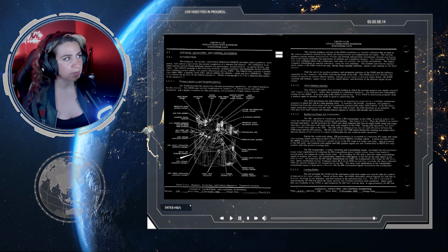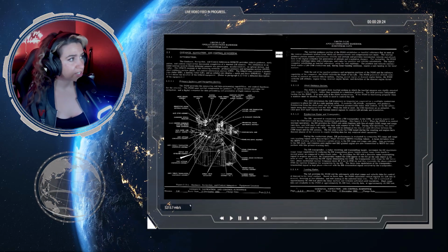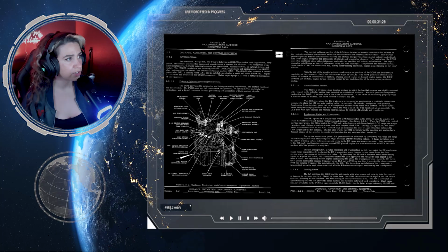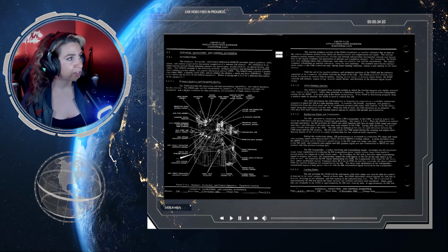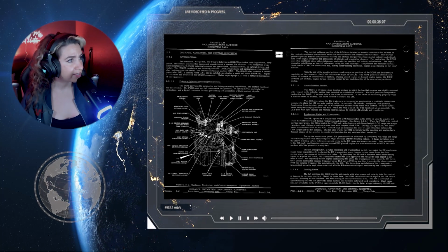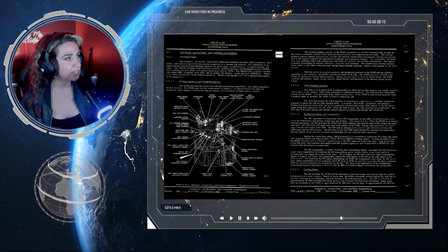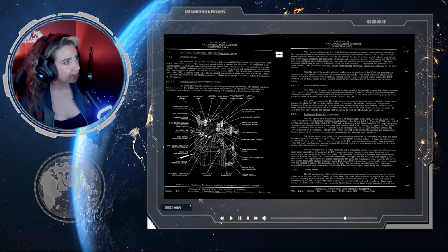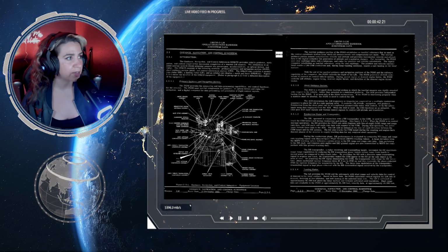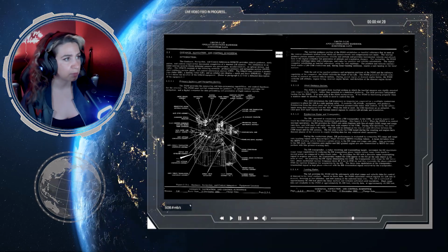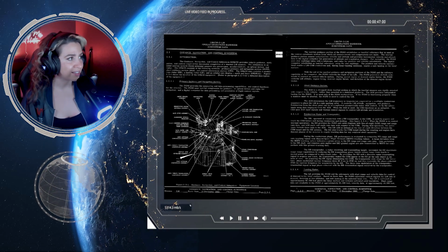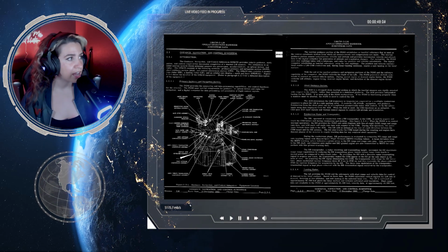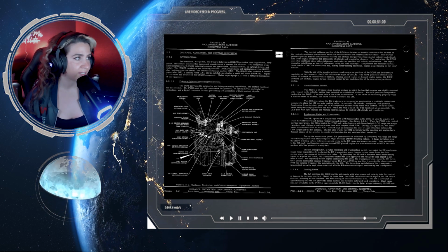The subsystem is an aided inertial system whose principal sensors are gyroscopes, accelerometers, an optical device, and radar. The GN and CS consist of the following sections: primary guidance and navigation section, PGNS, abort guidance section, AGS, and control electronics section, CES.